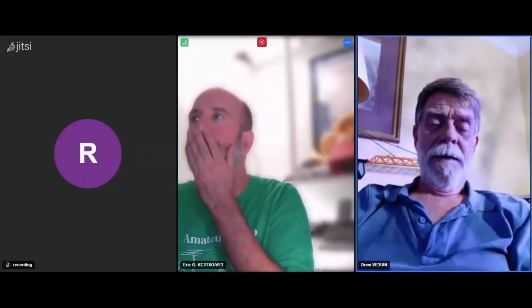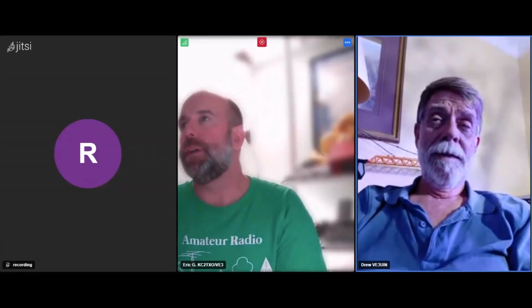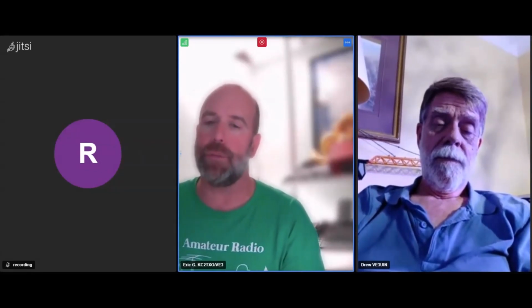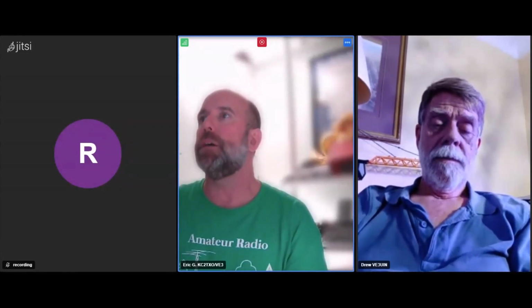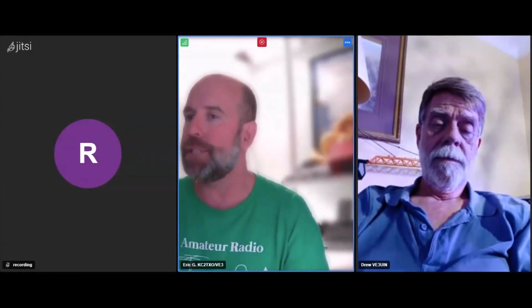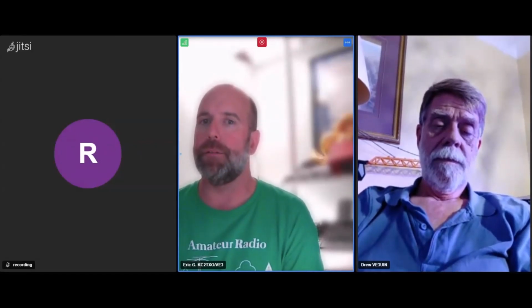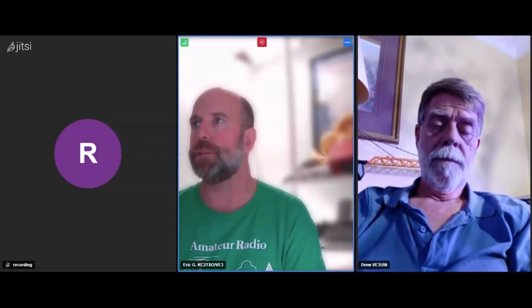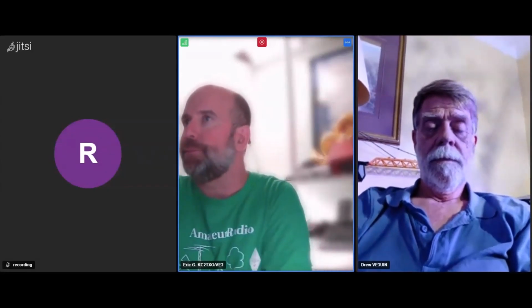Yeah. And then you changed out the coaxes, so that part's good. Right. Although I do want to run the Nano VNA or maybe the Rig Expert on the coax, because I know it can do some tests there. But like I said, I think step one is validating the Rig Expert, its actual function, because this is the first analyzer I've ever owned and spent any real time with.